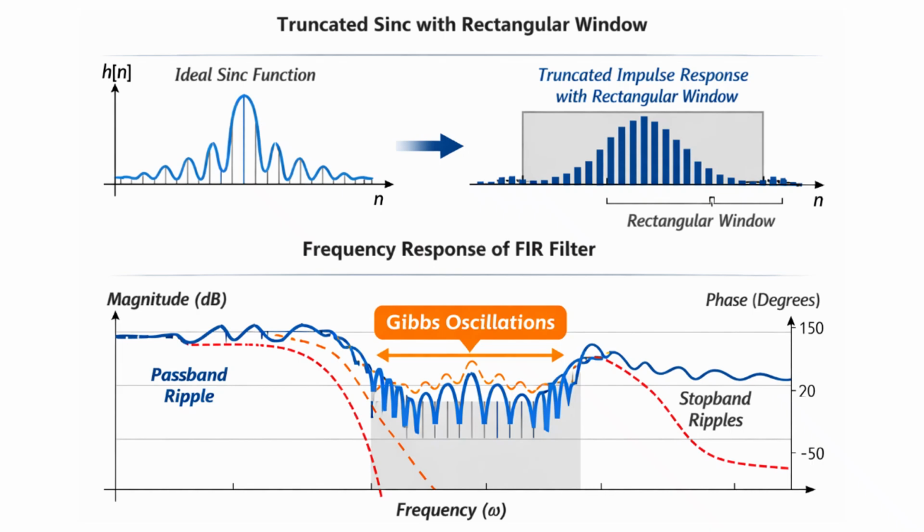Some more detail about it. Suppose this is the actual magnitude graph. If you look at the filter, it will have a zigzag. Why is this so? Because of the impulse response of the rectangular function. Whenever you take the Fourier transform of the rectangular function, it will be a sinc function, and due to that these types of ripple will come. This is called the Gibbs oscillation.